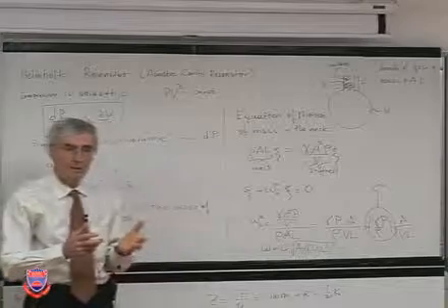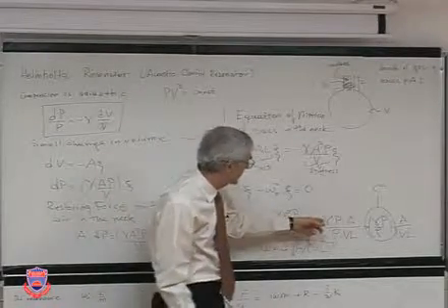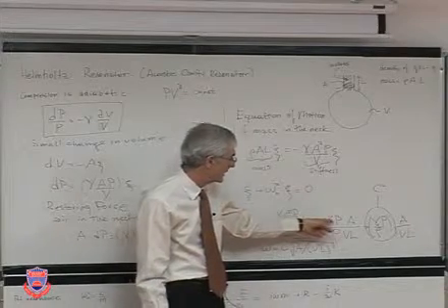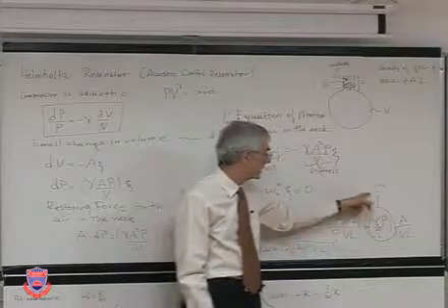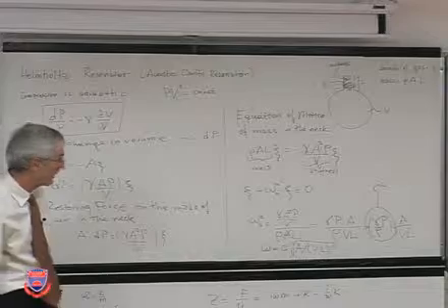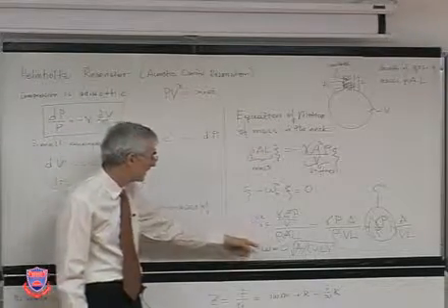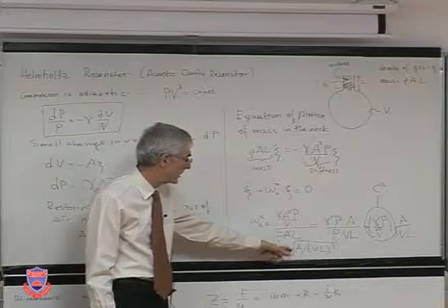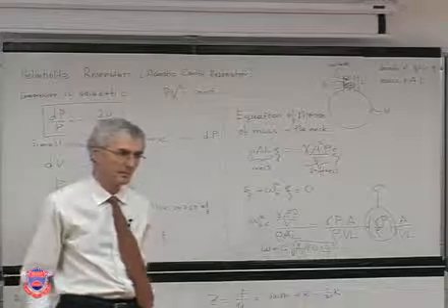But what is interesting here that you probably did not know before is the ratio of the specific heats multiplied by pressure divided by density is equal to the square of the speed of sound. Okay? So in this system, the cavity resonant frequency is determined by speed of sound and essentially the geometry of the system.